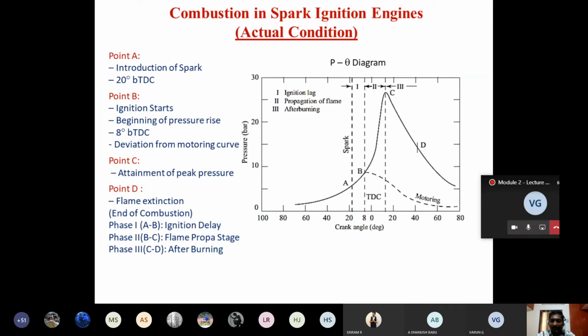That means the piston is going to move up and down. So one or two cycles we will be doing like this. In the meantime, the lube oil pump is started and the cooling water pump is started, so this will provide better lubrication. Before cranking a huge engine, lube oil pump and cooling water pump are started. This ensures lube oil movement everywhere inside the engine cylinder, between the piston and cylinder. Then after doing some 2-3 cycles, we go for cranking the engine.